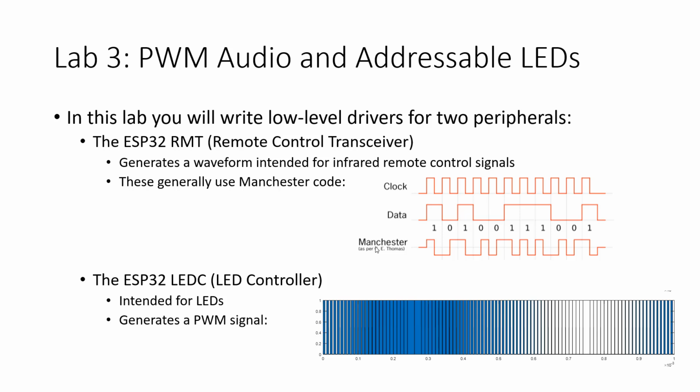And the other thing is that you're going to write the driver this time. You're not going to use any kind of driver support from the Arduino framework. You're going to write low-level code. So all of the interaction with the peripherals is going to involve control and status registers, right? Writing to registers, reading registers, bit twiddling. There tends to be a lot of that when you write a driver. And so this lab will give you an idea of how much of that kind of bit-level interaction you have to do to actually implement a driver.